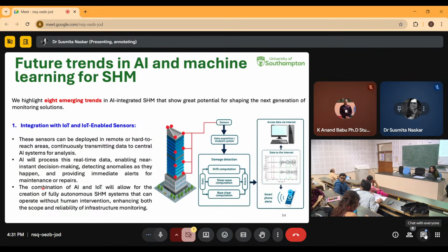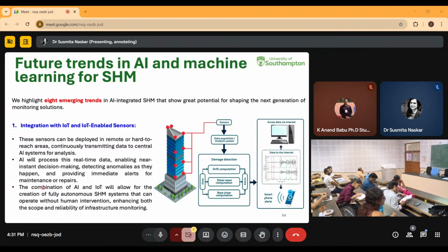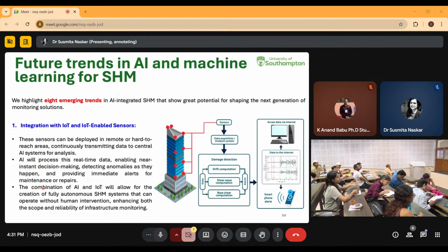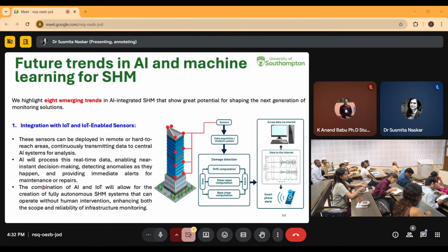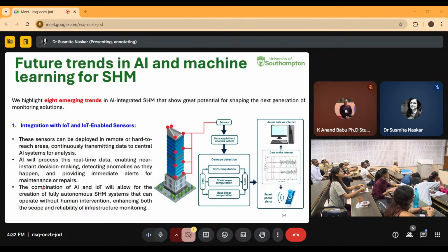Because right now we do not have a lot of SHM capability, especially when we talk about the large-scale one. We need to have sensors, and they are very costly. A lot of people don't know about sensors. Once we have enabled an infrastructure where the use of sensors is as common as other methods of structural testing, like vibration testing, then we can think about more things. It's all about the sensors being cheap or easy to install. Some are brittle, like PZT ones, and one sensor costs 1,000. And then it does not run for a long period of time, right?